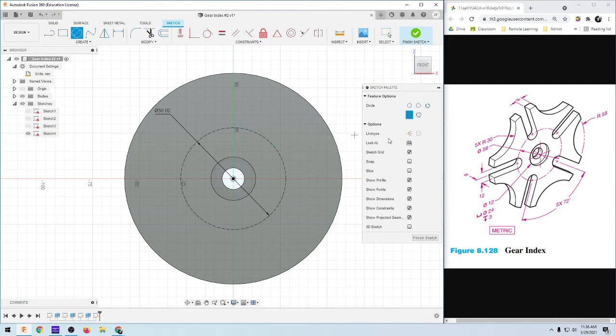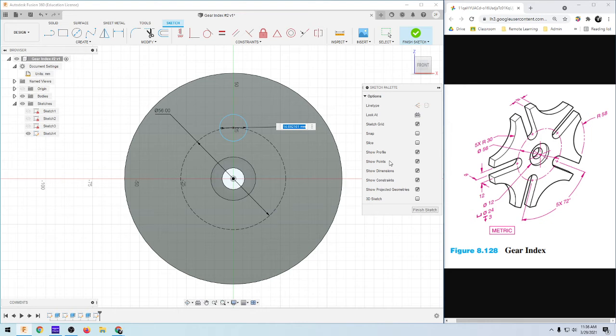Now I'm going to create my circle. Just like Onshape and just like SolidWorks, you can go to a point and then drag it up from there, and it will lock in. It'll be snapped onto that point. I want it lined up with the origin and here, and then it snaps on there. That's good. And now I'm going to dimension this out, and we have this dimension here, which is kind of an awkward way to dimension this, but it is 12 millimeters, so it's 12 millimeter diameter.